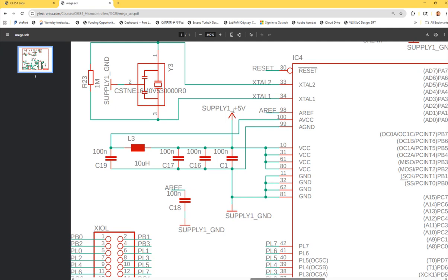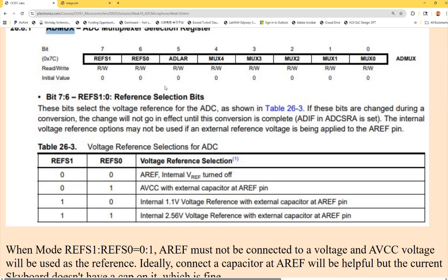256. Okay, you have to know. AVCC is shorted to the power supply, so you know it's going to be 5 volts divided by 1024. 1024 is very close to 1,000, so you can quickly calculate that. The smallest voltage that can be resolved by this ADC will be very close to, what's that? 5 millivolts. That's the answer I want to hear.